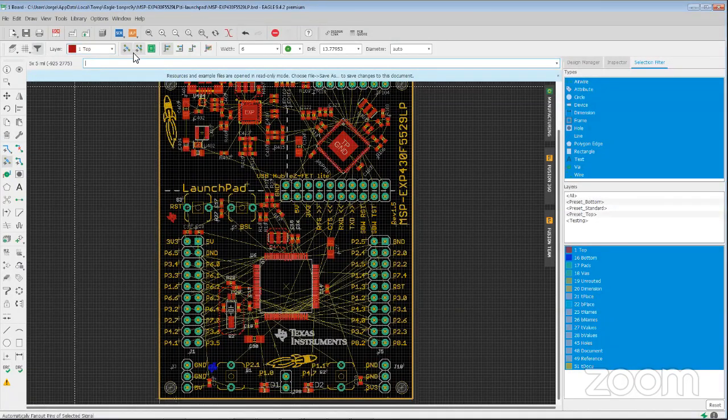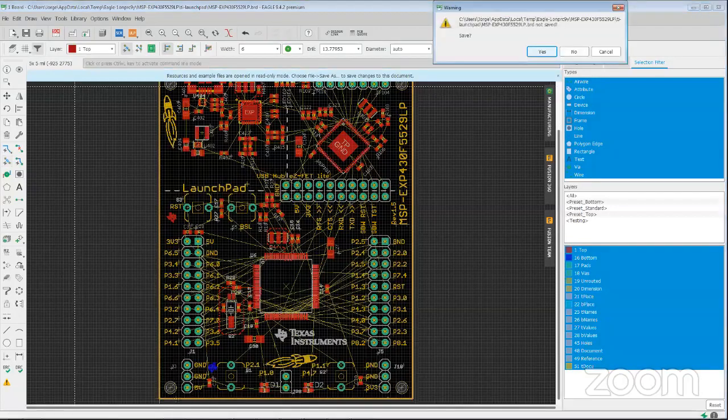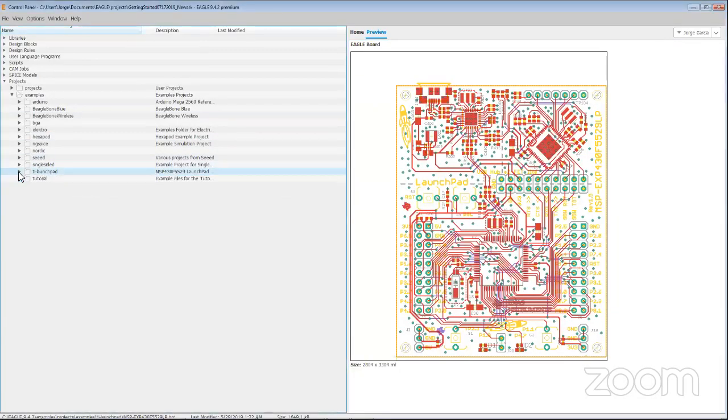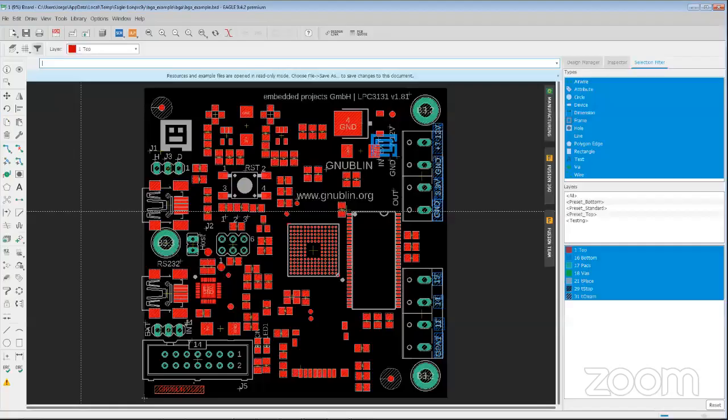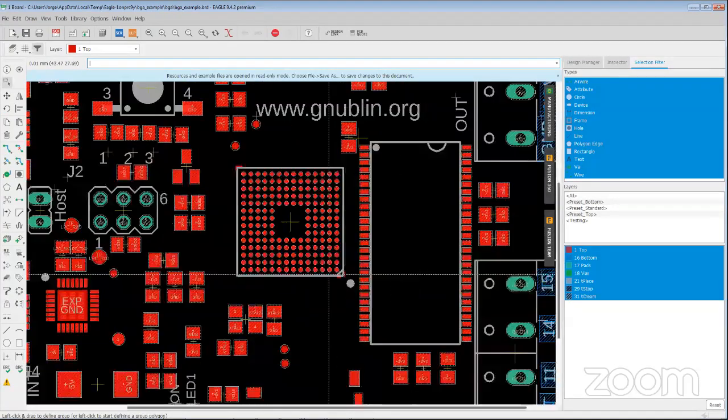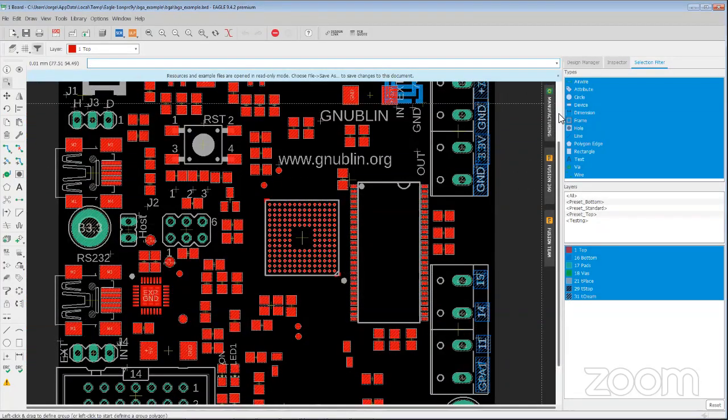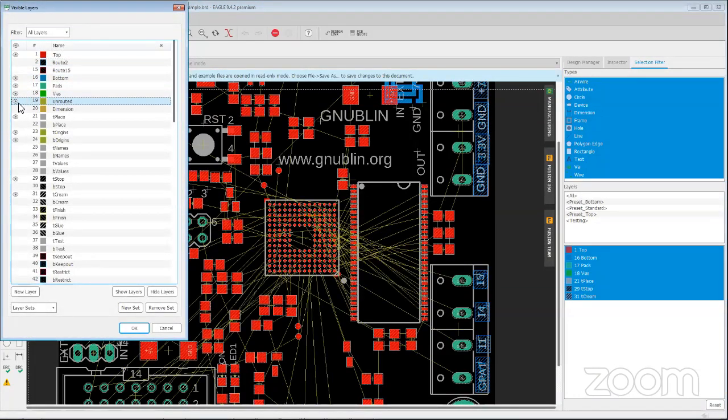So in this video, we won't be showing how the BGA auto router works. Actually, let's show it. Change my mind. I'll do it with the example that comes with Eagle so you guys can see it. I thought you were going to break out maybe all the grounds or something like that. I'm still going to do that too, but since I started with the BGA auto router, okay. So now let me make sure all the layers are on. There we go. That way we can see other stuff to connect.